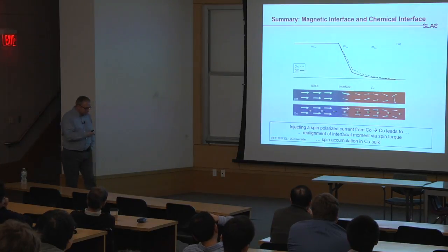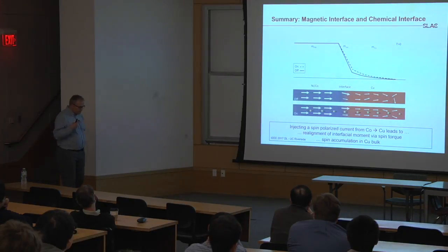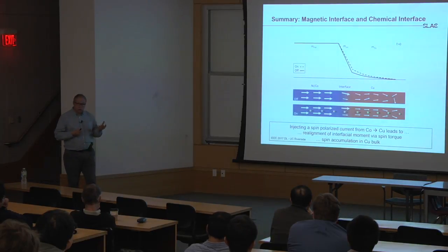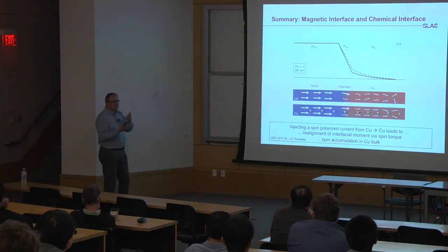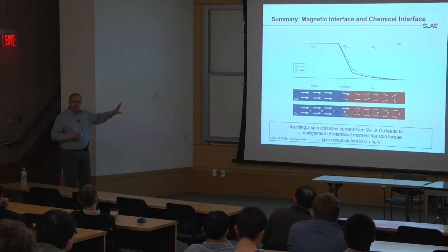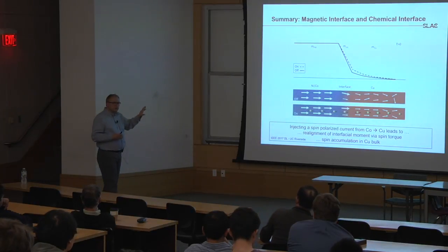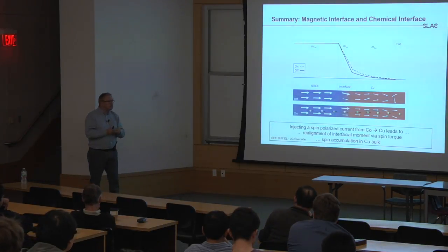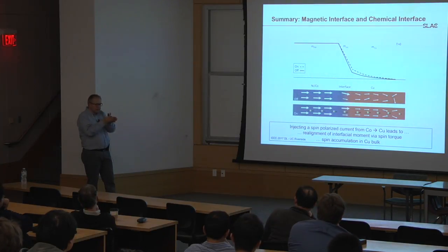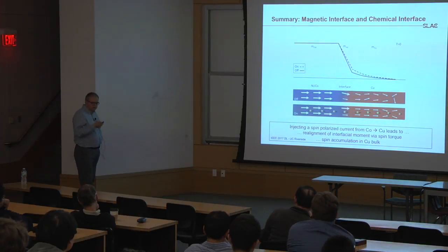What's interesting about this is that people knew from experience for many, many years that you never achieved the spin injection efficiencies that you would hope for from theory. It was always about 30%, 50%, something like this. And I think this really showed us why this efficiency is limited: you have a magnetization at the interface, and when you run the current through it, you already lose most or half of your spin polarization, because you use it by remagnetizing this interface.